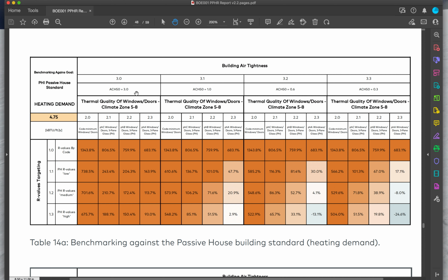Now, you see at the top here the level of airtightness that we get, 3 ACH. While there's a lot of builders that complain about it, that is code minimum for the 2021 energy code. And it's actually pretty straightforward to get to. But I would consider that a deep failure on me if we only get to 3, as well as if I only got to 1 ACH.